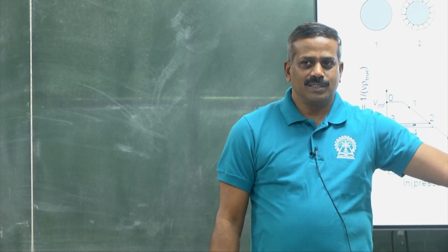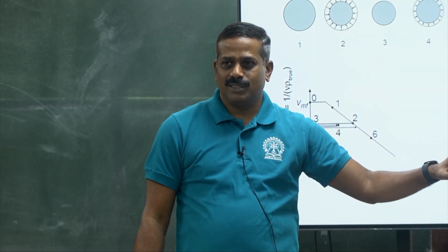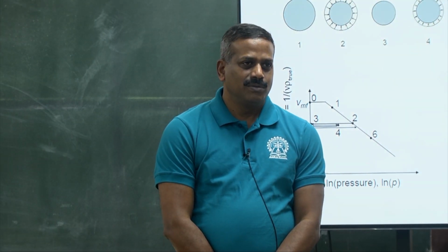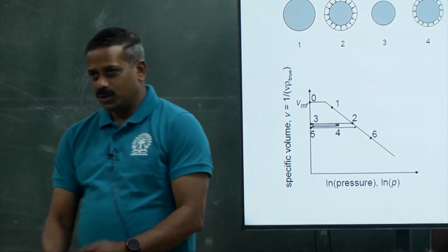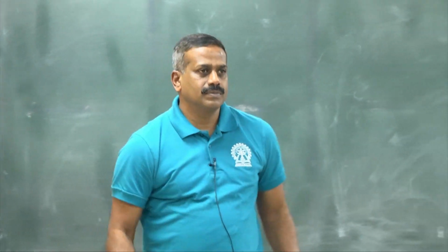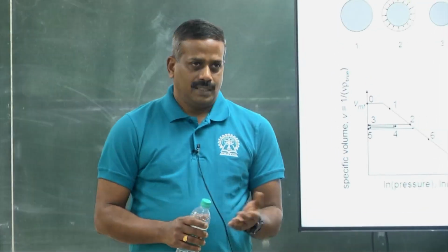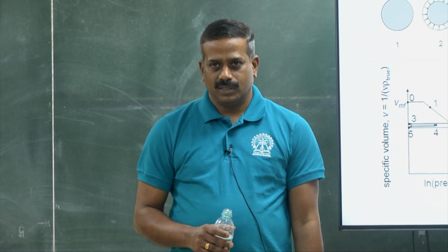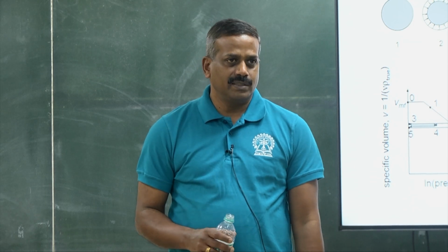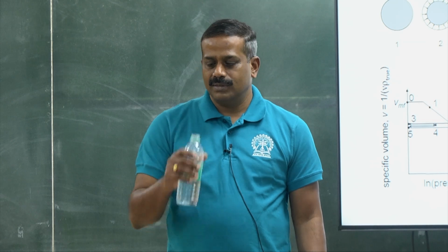Don't talk about shipping and handling, we are already done with that. Any other examples that you can think of where you should know the void fraction of the bulk powders? Yeah, dissolution rate. One common example is dissolution rate. If the void space is high, then the dissolution will be higher. Any other examples?